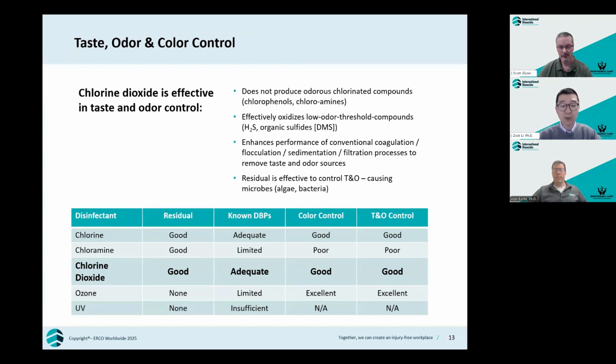Chlorine dioxide treatment can also control many other taste and odor causing agents. Chlorine dioxide degrades phenols by direct oxidation to form harmless, taste and odor-free compounds. Chlorine dioxide effectively oxidizes hydrogen sulfide and many organic sulfur compounds.